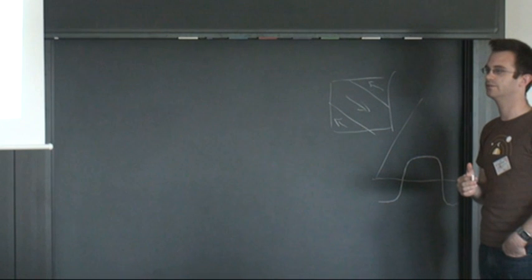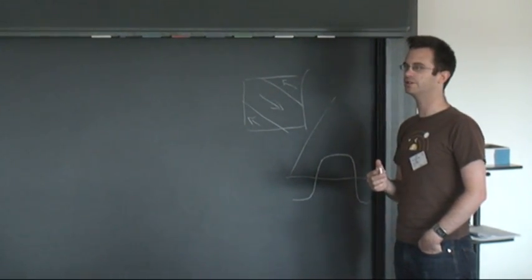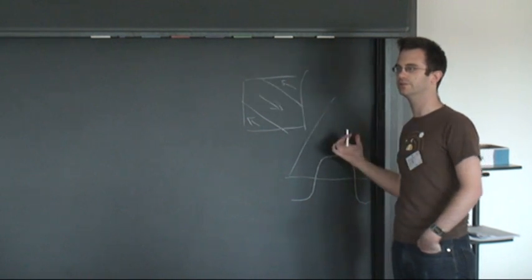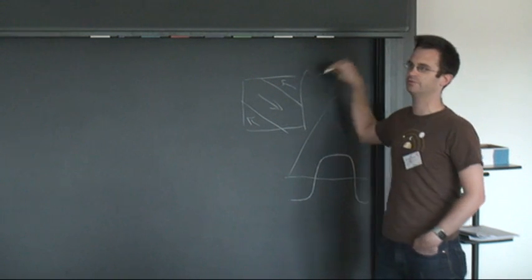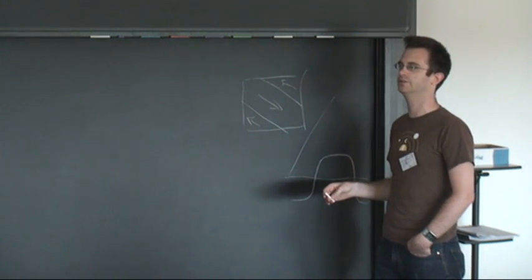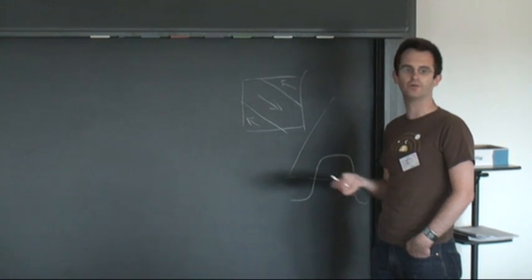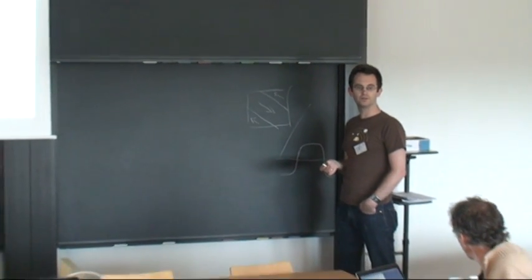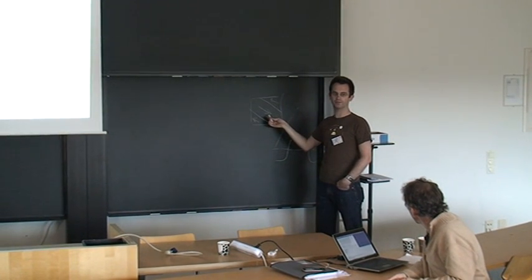But how do you know what it's supposed to do? There are no perturbations here. It should just run smoothly. This is just fluid going this way and fluid going this way. There's no cross-stream perturbations, so nothing should. Cross-stream perturbations should be identically zero, so they should never become unstable. Sorry? It must become unstable. But that is from grid effects only.